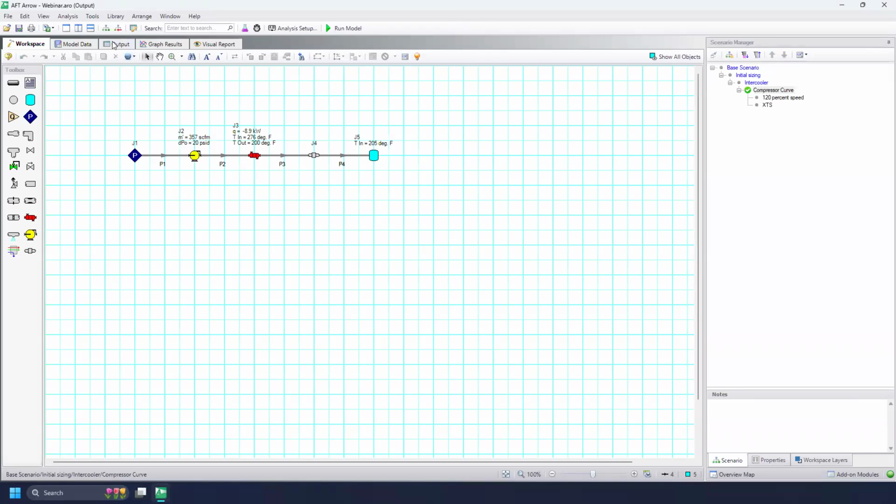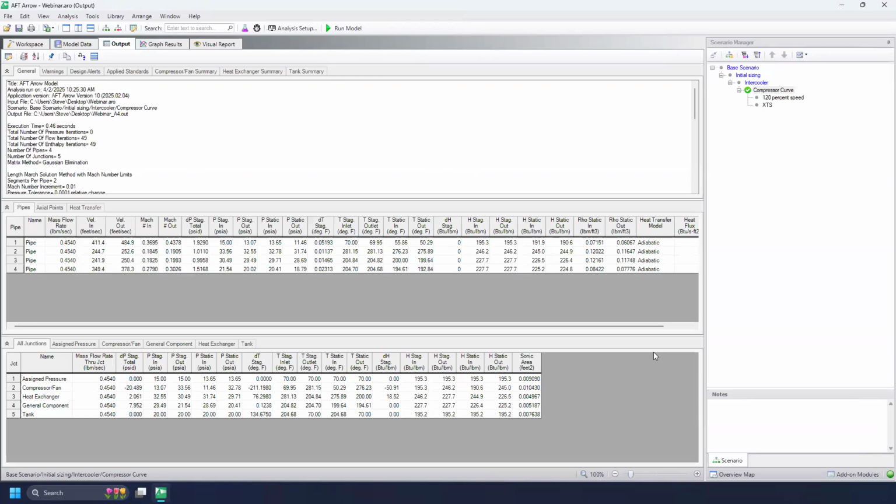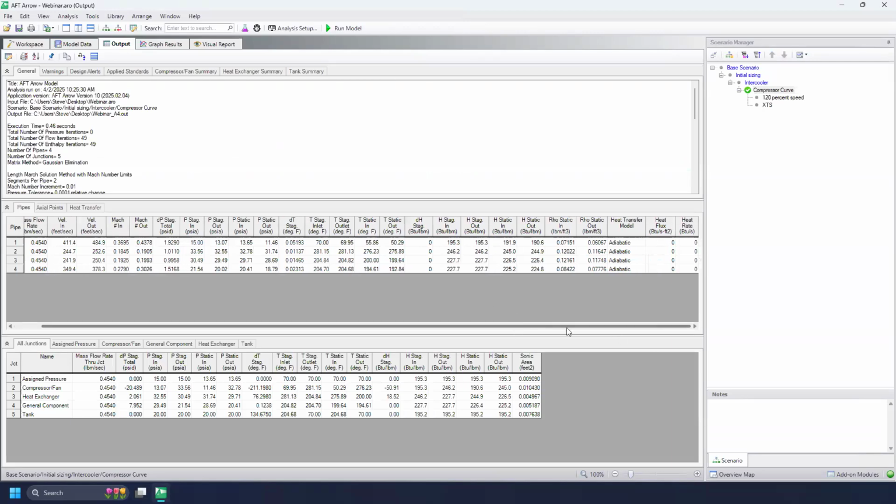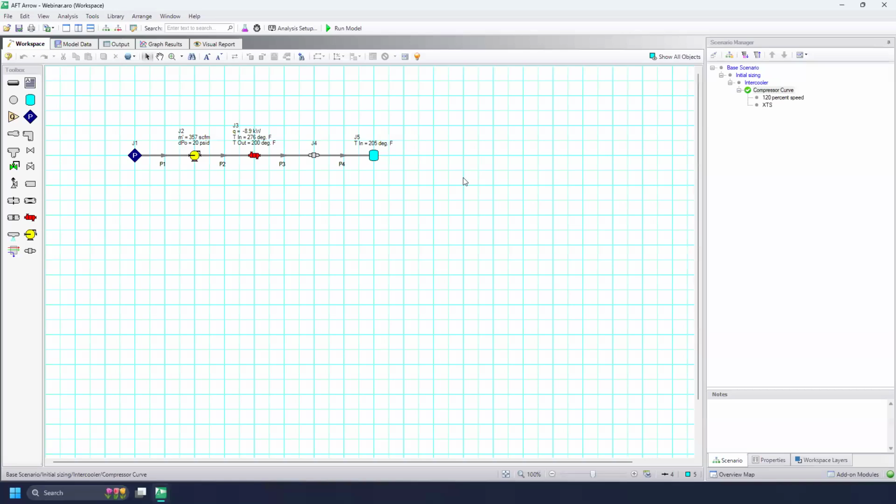The stagnation enthalpy is staying constant here, but because it's a real gas and not an ideal gas, the temperature is actually changing because we have the density changing as a result of that pressure loss. So because of the friction, we don't have quite the same temperature, but in an ideal gas, you would be correct. You would expect to see the same temperature there.